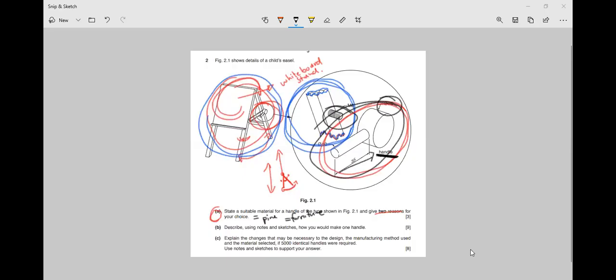But now you have to think, this is a piece of threaded rod, right? Yes. Is it going to take hammering or not? It might, to knock it into the wooden leg. Okay, so it can pick up damage, right? Correct. Then in that case, aluminum might not be a suitable material.